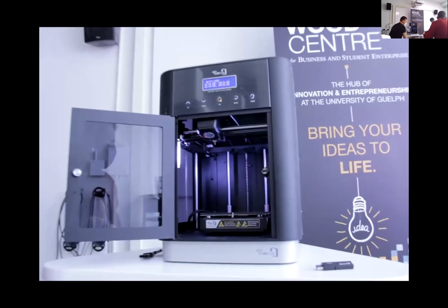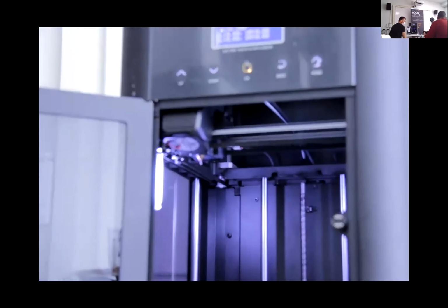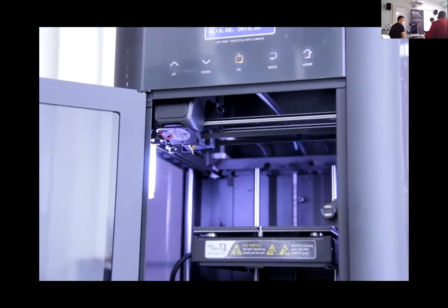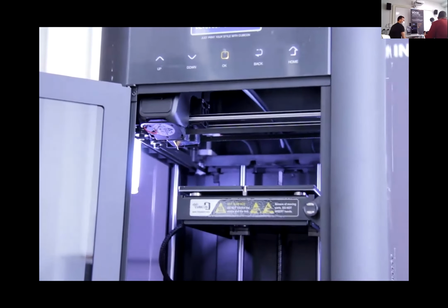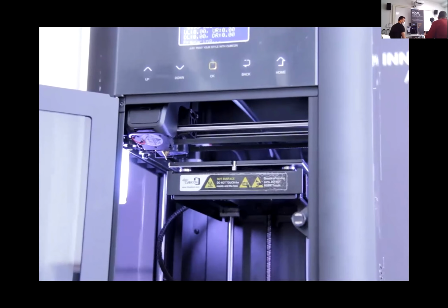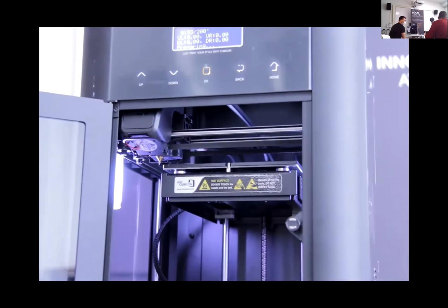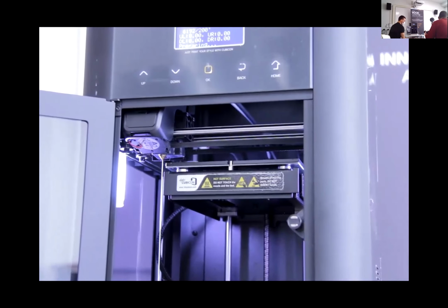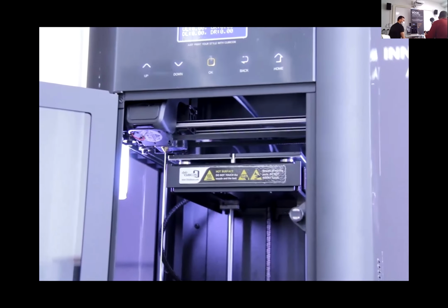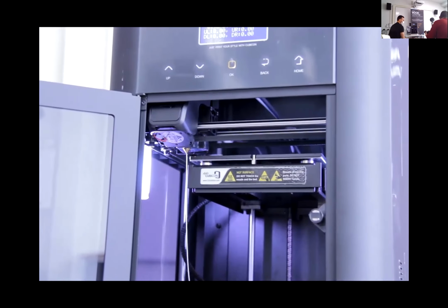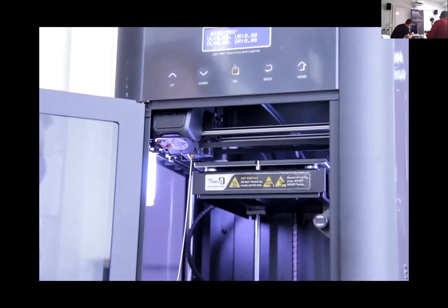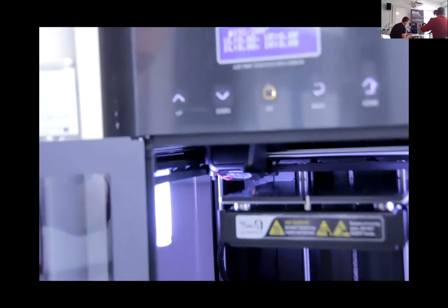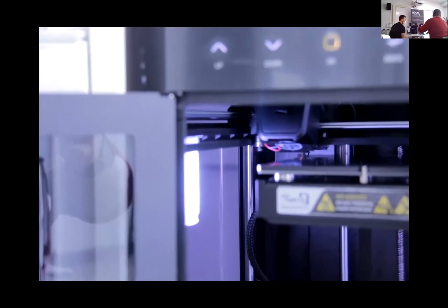And this is another very important thing for 3D printing to keep in mind. You never want to leave your printer while it's printing, especially on the first layer. So the first layer of plastic that's put down is the most prone to not adhering to the build plate and messing up your print and clogging your printer. Oh, might need to be realigned a bit there, actually. It's all good.